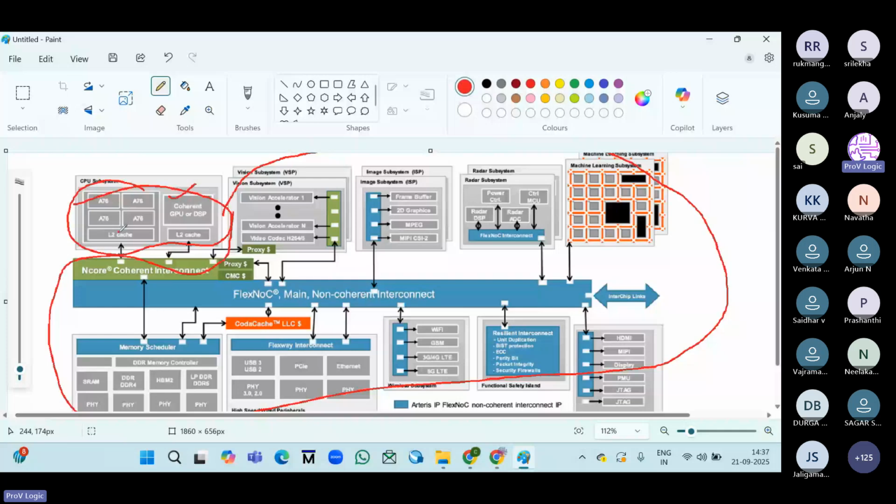But whatever instruction set architecture we are writing, that cannot be verified using SystemVerilog or UVM. We can verify it only with C or C++ test cases. Sometimes, not even nowadays but from the past few years, this is also verified using C language. That C language, verified with SV UVM, can be converted into C++ also. There is a concept called the Direct Programming Interface, DPI. By using this concept, we can convert SystemVerilog test cases to C language and back to SystemVerilog. That's another thing.